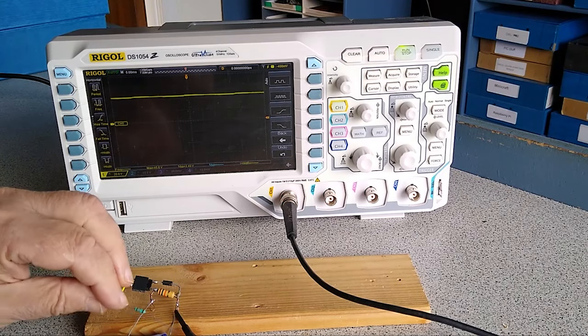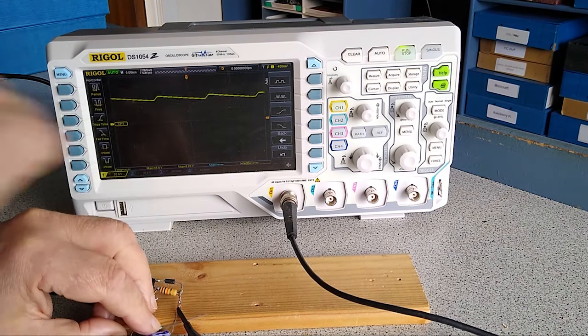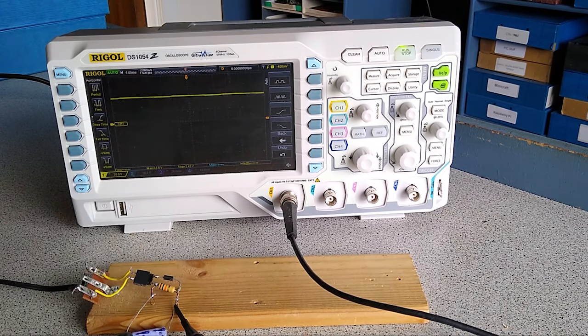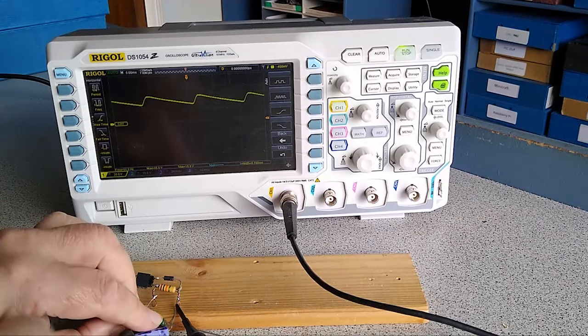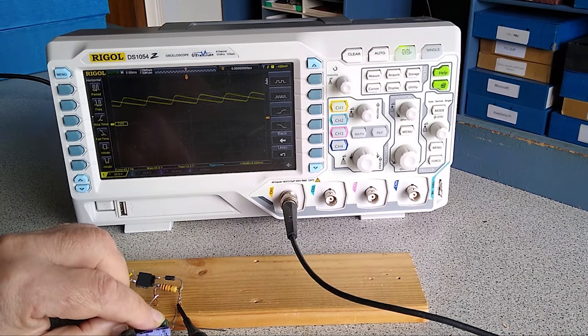If I start to draw excessive current, however, you'll notice the pattern changes. The capacitor isn't able to store a regular DC. You're getting a hum. If I put an even greater load on it, we get an even greater variation in the output.